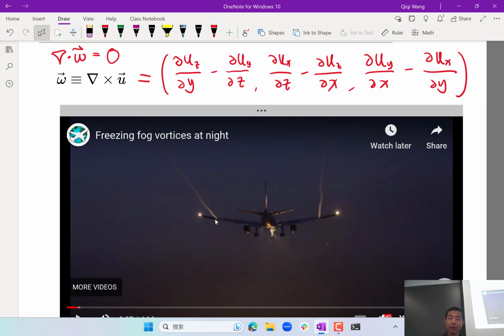In particular, this ends on the junction between the extended flaps and the outboard portion of the wing, which has no flaps. So basically, the gap between a higher lift region and a lower lift region, in the takeoff and landing scenario, is where the strongest vortex comes out from the wing.